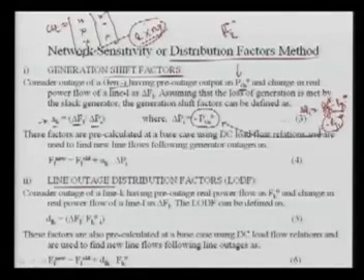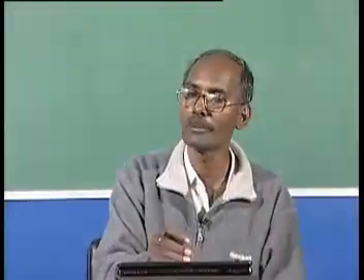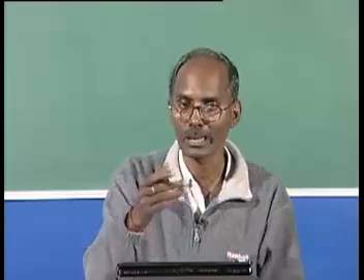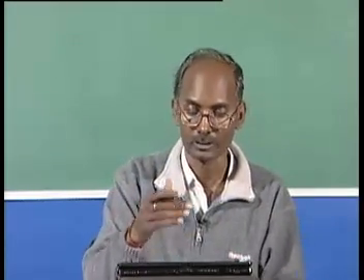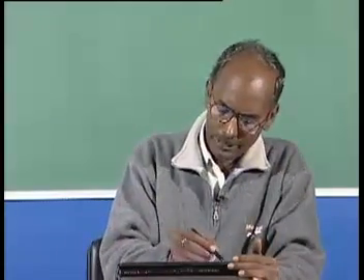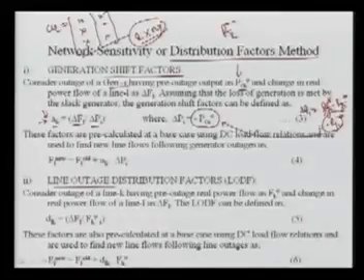All these factors are calculated and stored in the computer, and they are calculated on the base case, meaning we are assuming the same loading, but the loading can change. Once you use them, the system loading will be different, but it is assumed that, although somewhat inaccurate, this will rank the transmission line outage cases by severity with reasonable accuracy. So as I said, we can calculate these factors at the base case, store them and use them. Now we can see how we can use them.